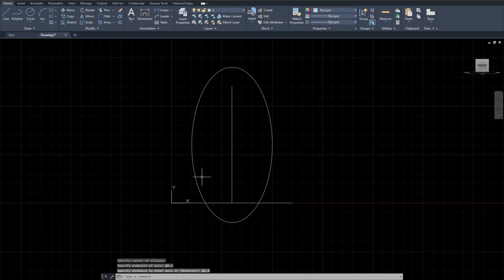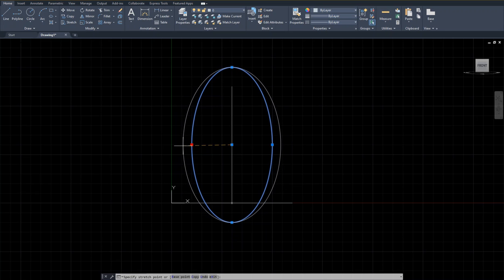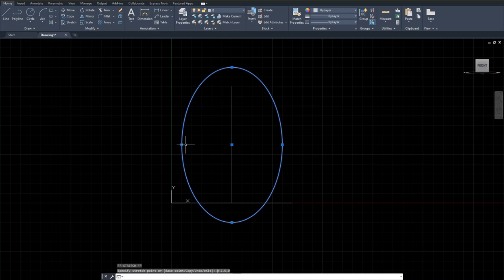And I'm going to even extend this line up to the top. I wonder if you can modify this a little bit more. You can always modify later. When you click on it, you have a control point, so you can just move it a little bit further away and make this a little bit more shapely. This time I'm trying to move this point, and let's make it 2.5. Add minus 2.5, comma 0. This is perhaps even better.